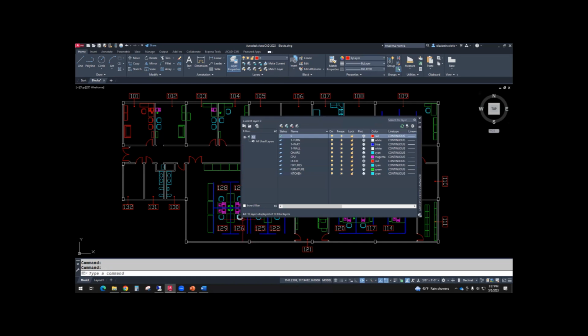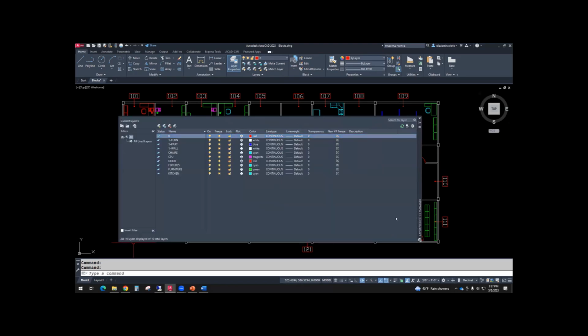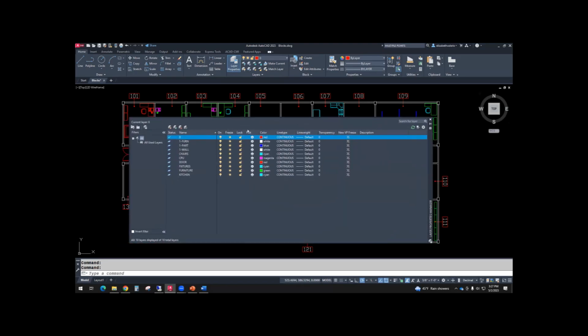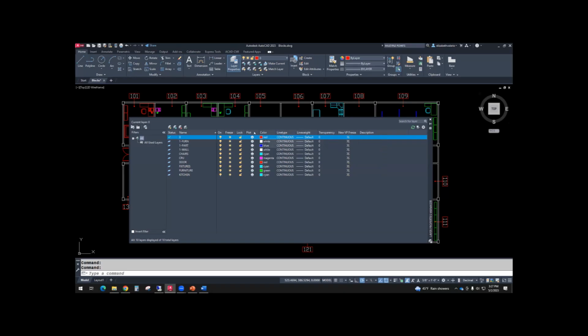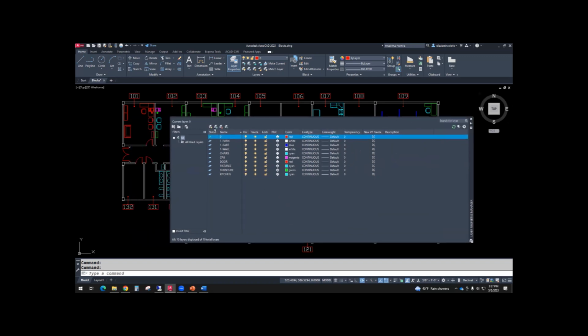And so this is the window we saw earlier with the parking lot. You can stretch it, make it bigger. If this is the first time you've opened this window, these columns might be all scrunched together. You can put your cursor between the column headers, click and drag to make them bigger. Or when you see the double arrow between the headers, you can just double click. Double clicking kind of auto adjusts those column widths. All right, once you have it so you can read all those headers, we're going to go through each of these columns and explain why it's important, what it's for.